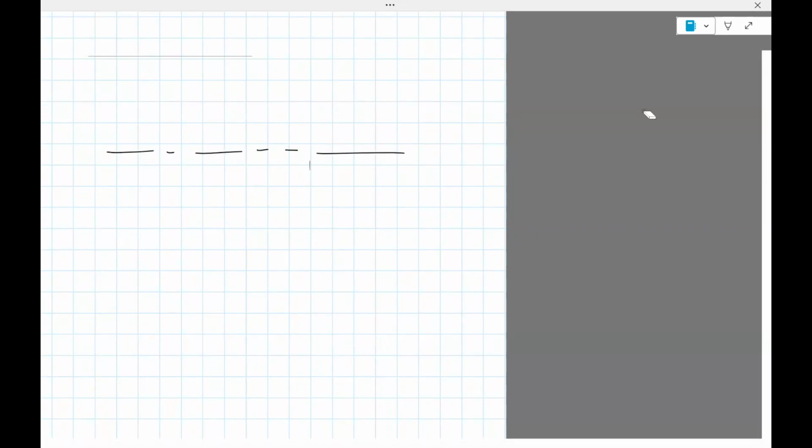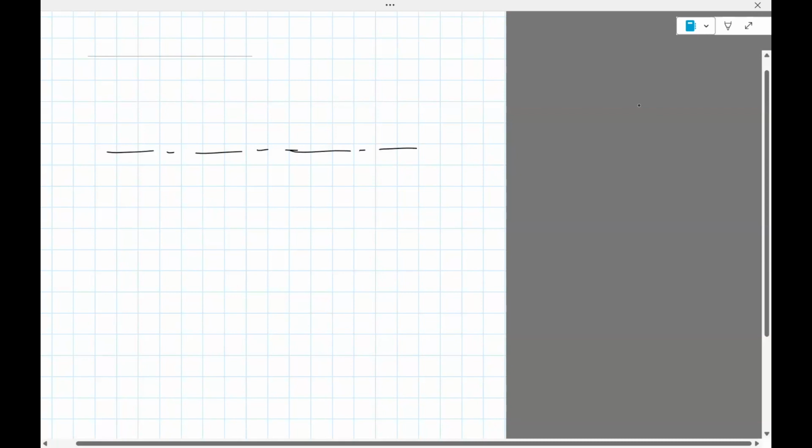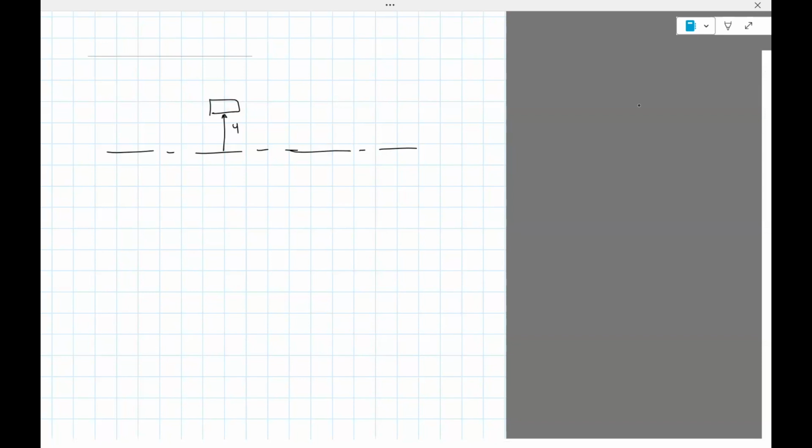In the neutral axis, this is the shear element at a distance of y1. This is the top, C. Okay, so we wrote tau equals VQ divided by I times B. Q here is actually the integral from y1 to C of y dA.